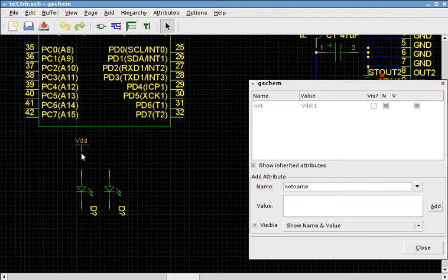Basically it is the point of connection, which is highlighted in red in a symbol, and then you press lowercase n to start the net, and wherever you go, the net will be connected. So we'll connect it here first, and unless I press the right click key or select another tool, the net keeps going and going. So now that we are done, I can either press the right click key, which is the same as escape, or I can just press escape as well. Okay, and now that I have pressed the right click key, you can see that I'm no longer drawing a net at this point.